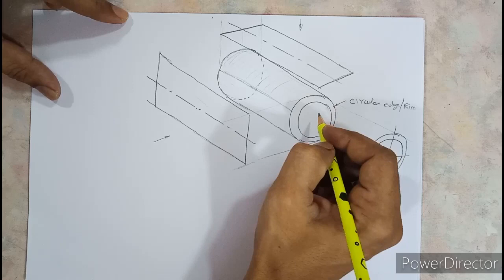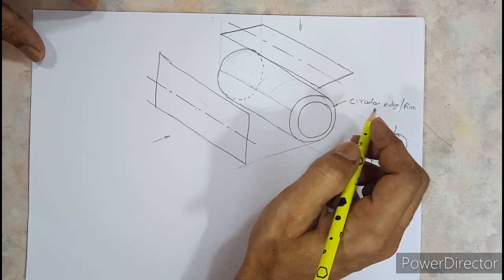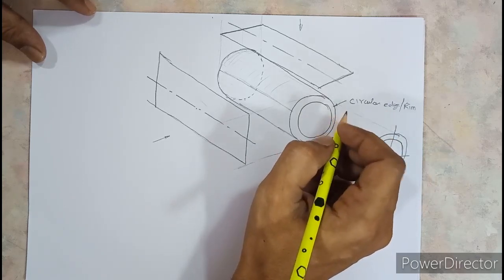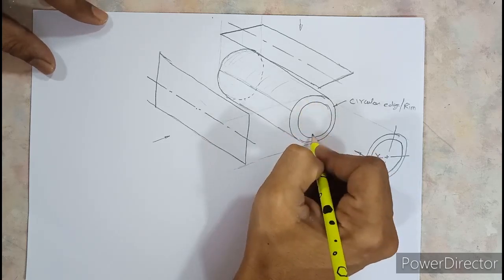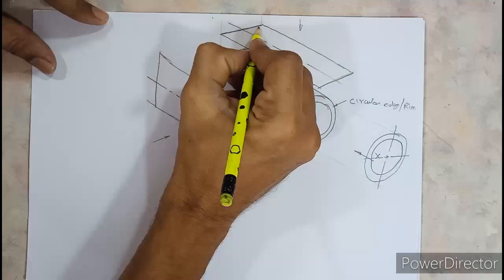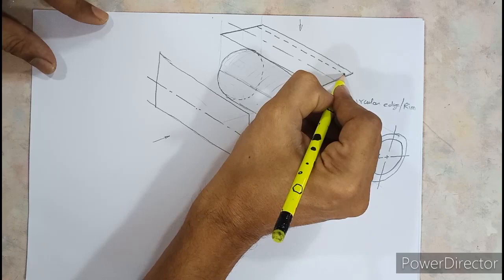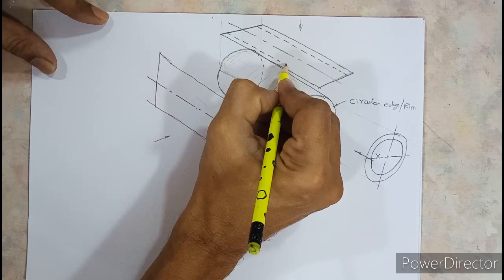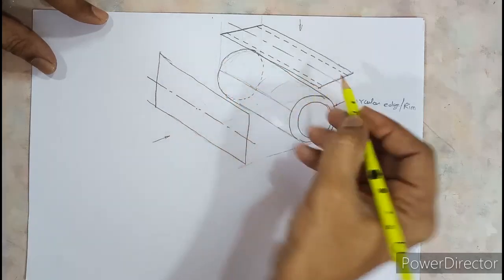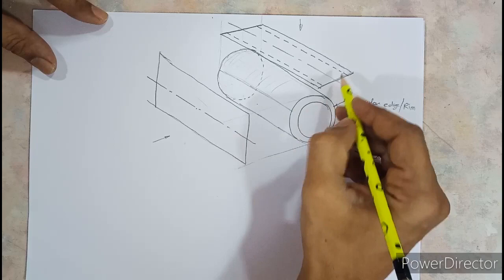And we know that the surfaces which are not seen in a cylinder or in any object are shown by hidden lines. And hidden lines are nothing but broken lines. So in the top view, you cannot see this circular surface. So we need to show a broken line like this. What does this broken line imply? It implies that there is a circular cavity going in throughout. So the distance between these two hidden lines represents the diameter of the circular cavity which is going inside.